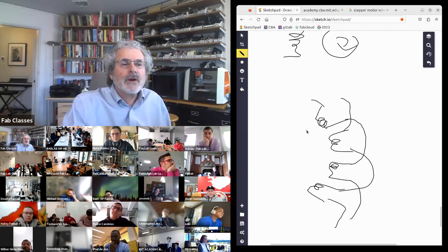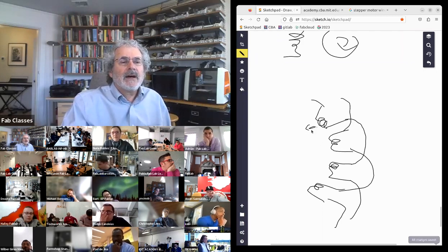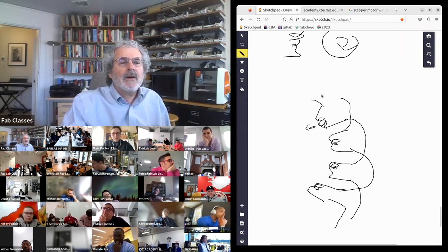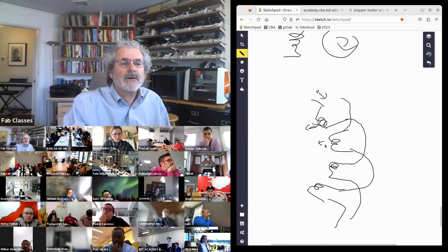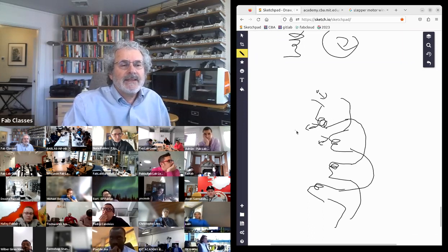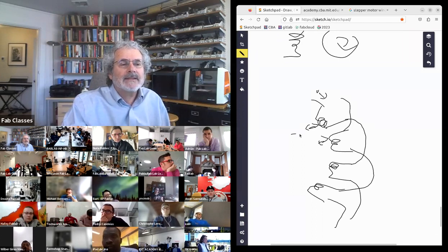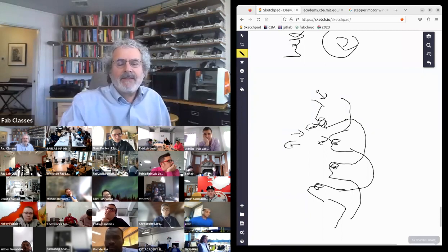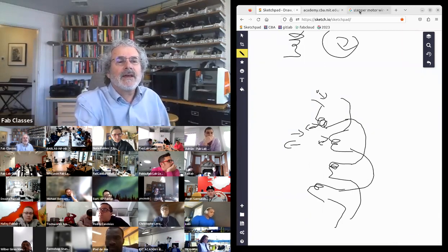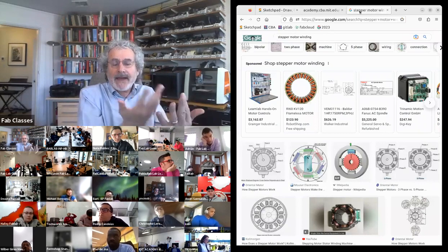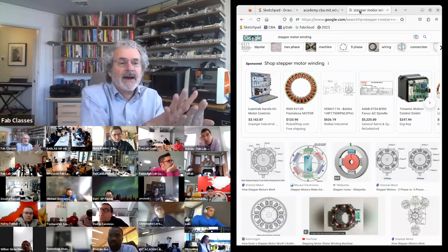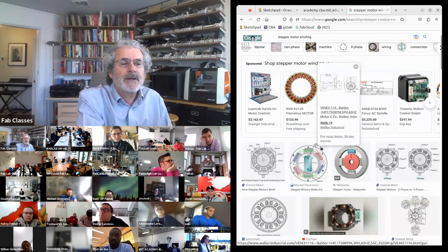And these are oriented so the magnetic field they generate goes this way. And depending on the direction of current through the coil, it can either point in or out. Then in here, in the rotor, I've got permanent magnets, and the permanent magnets can point in or out. And then these are chosen so that the ratio of the number of magnets to the number of coils doesn't divide, so they slightly overlap.